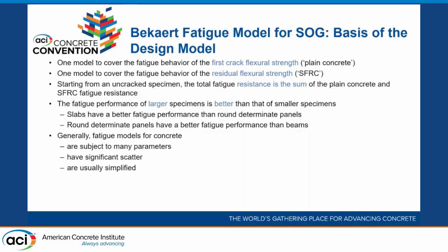So this is, in words, the way we approached it. We have one model to cover the fatigue behavior at the first crack. So we start with uncracked concrete and determine at what point it cracks from fatigue, not from load. When does it crack from fatigue? Then the second model takes over from that point to the final life of the element.